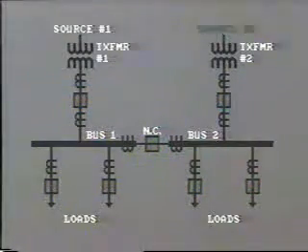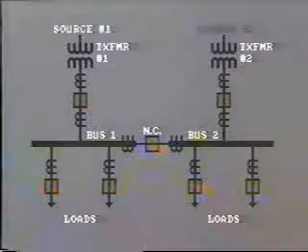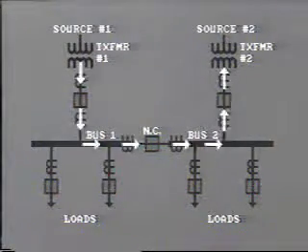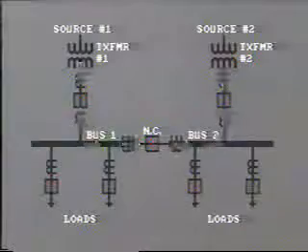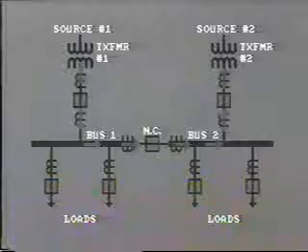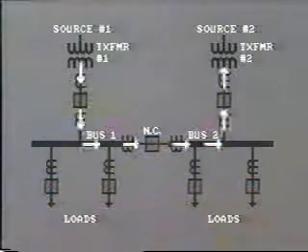For example, line 1 and line 2 may not be fed from the same bus or even the same location. Consequently, there is probably some phase difference between them. In this situation, line 1 may try to transfer load to line 2 through transformer 1 along the connected bus and back through transformer 2. This is a highly undesirable situation that may allow extremely high currents to flow through the system. For this reason, you will often hear the recommendation, never connect transformers in parallel.